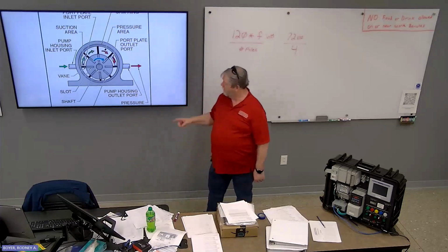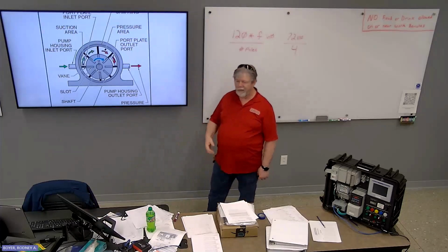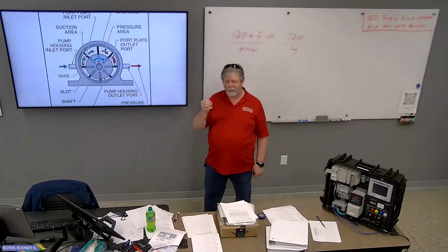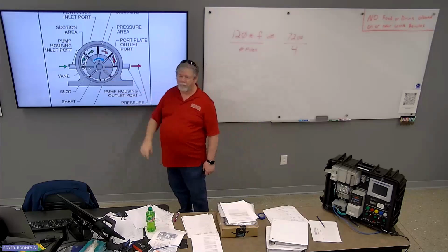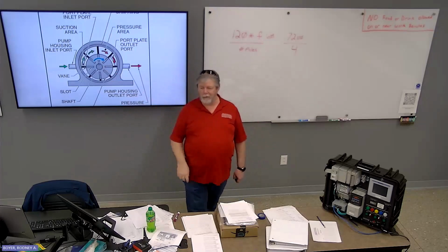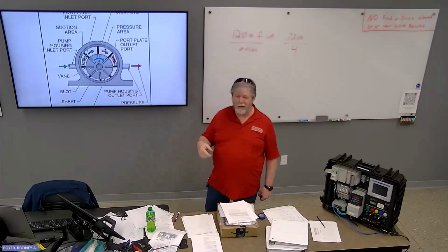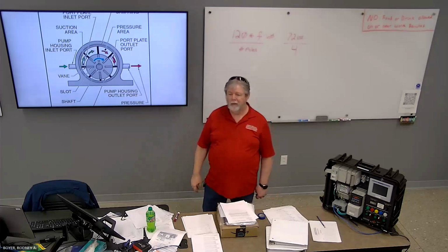Yeah, as the rotor spins, the vanes expand and contract. They're spring loaded, so it keeps them in contact with the housing, and then of course, once you get it spinning, there is centrifugal force there too.